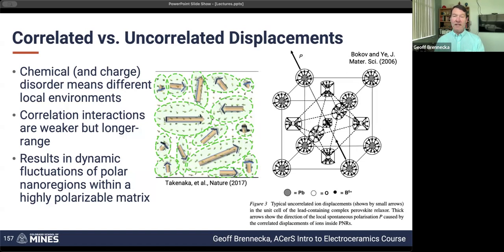And as a titanium replacement, it is an acceptor, a double charge acceptor. And so that's one of the nice things about those amphoteric dopants, as they're known. They can go on either site. So you can either go on the A site or the B site. Sometimes that just means added chaos and it's hard to know what's going on.